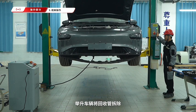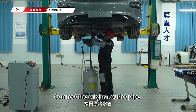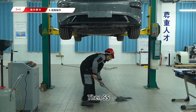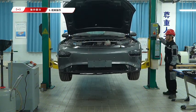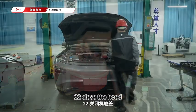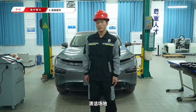Lift the vehicle. Remove the recovery pipe. Connect the original outlet pipe. Then 5S. Twenty-first, lower the vehicle. Restore the expansion tank cover. Twenty-second, close the hood. Clean the vehicle. Clean the site.